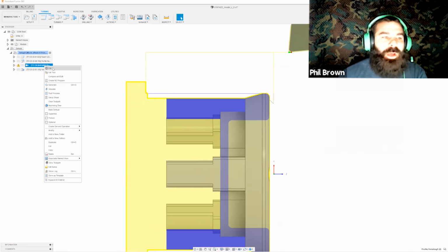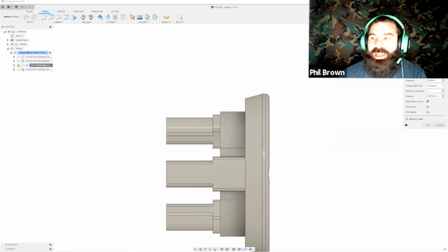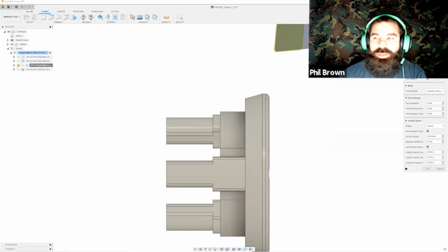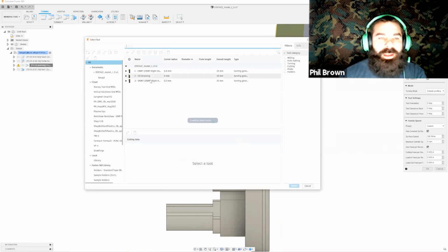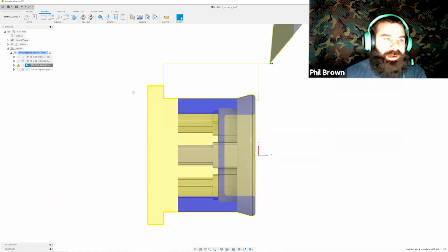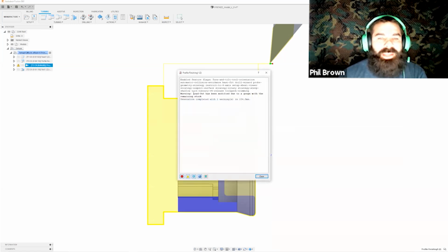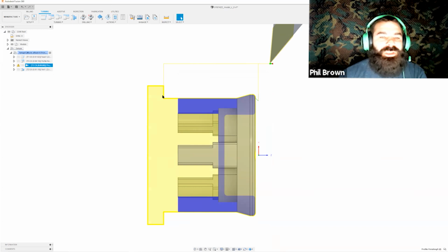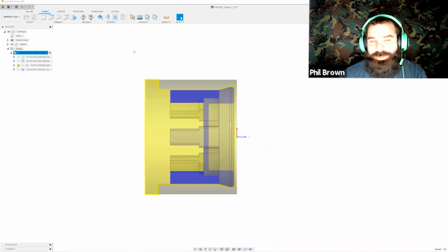From that, I do need to swap my tool into my cleanup cycle. I also need to turn on my axial and radial grooving so that that tool makes it all the way around. Again, I used a template to get to where I'm going very quickly and get about 80% of the way there, and then I can come back and make some changes. One other thing that Fusion 360 is doing for me is giving me a warning: the lead out was modified because of gouging. So it even looked at my roughing profile and warned me that it had to make a change because that tool's going to collide with that roughing stock. I can edit this to get rid of it, but I like to leave it there for demonstration purposes.